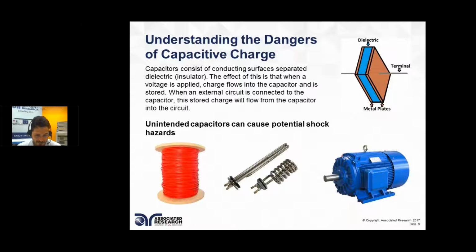And so when our customers are high-potting these long spools of wire, they may not be taking the proper steps to discharge this spool. The first person to come into contact with it, or we're told stories of the forklift operator who picks these up, they're always getting dinged, or always getting shocked, because you've just charged this huge capacitor and didn't take the proper steps to discharge it. I'm sure the next question is, well, what are the proper steps to discharge it?